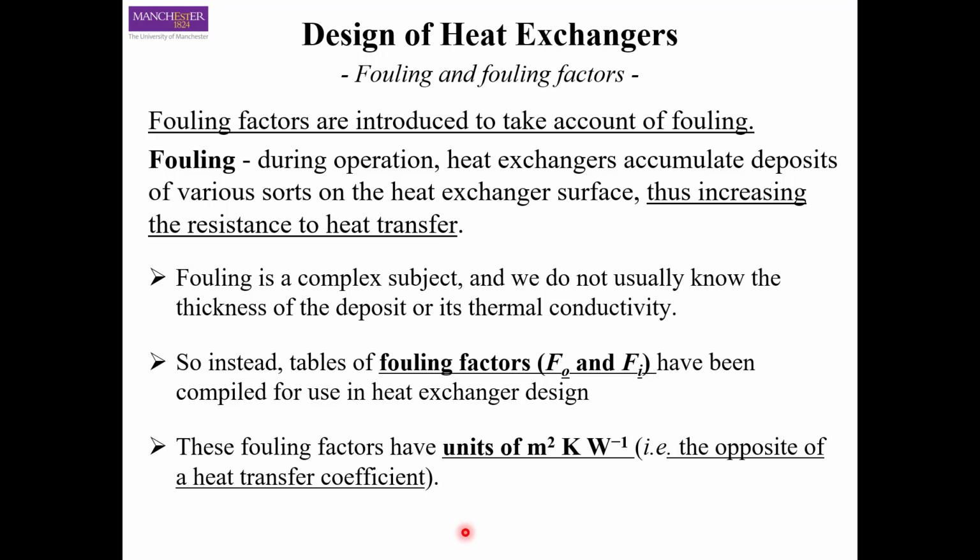So fouling factors are actually introduced to account for the fouling, because fouling is quite complicated. If you have fouling in your system, we are not sure what is the thickness of that fouling layer, and we are also not sure what is the thermal conductivity, because we are not sure what is the mechanism of that fouling layer. It can be one mechanism, but at the same time it can be multiple mechanisms all acting at the same time, like biological fouling, rusting, scaling, all can happen at the same time.